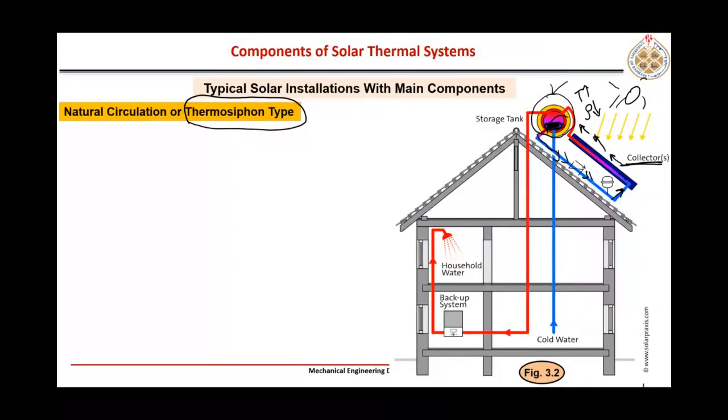The cold fluid is coming down by gravity, and the hot fluid, because its temperature is rising by absorbing solar radiation, has a dropping density, so it will start to rise up. So cold fluid is pushing from the bottom, and hot fluid is going up because of the drop in density. So natural circulation will be set up in the entire system, right?